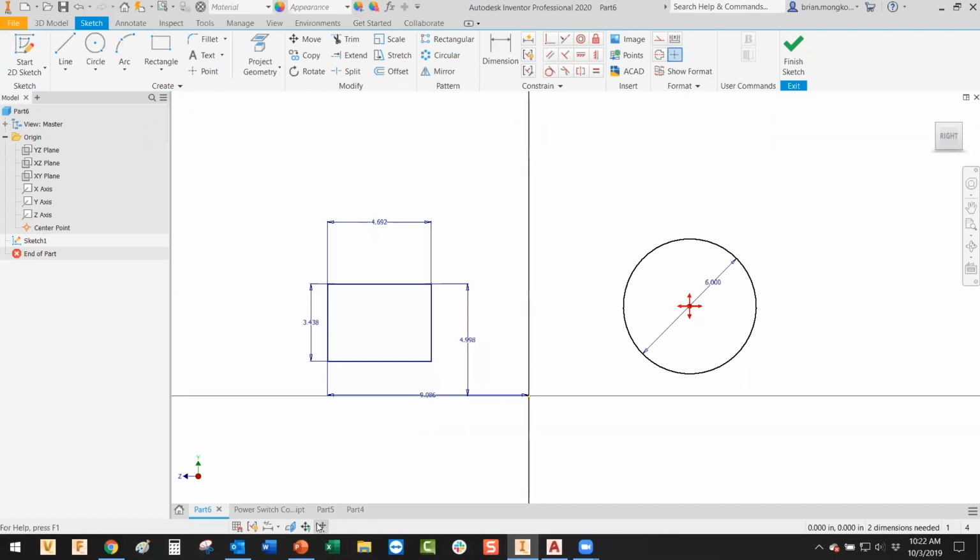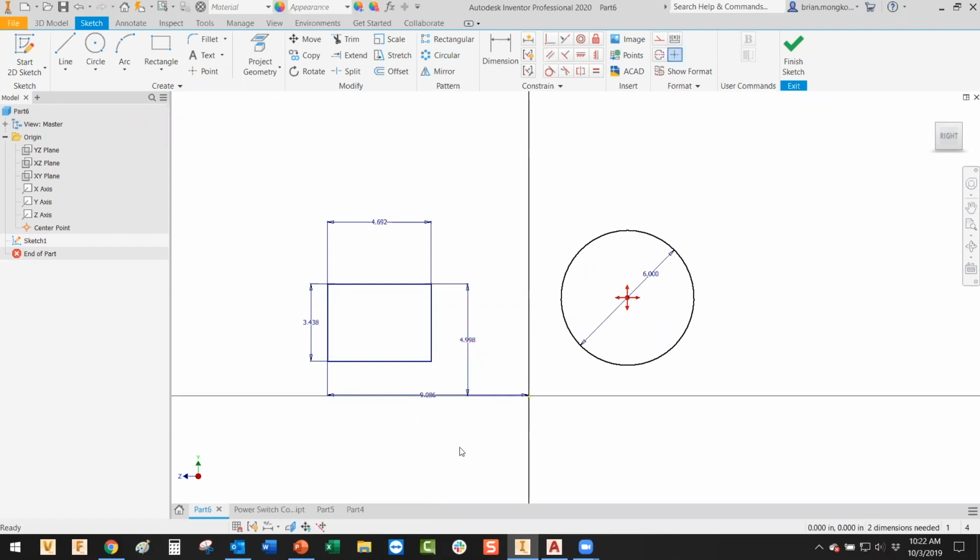Yeah, I think this is underused sometimes, and people forget about that. But when you're sketching and defining your sketch and you're almost done, just turn this on and see where else it's missing. I just lock it. I'm bad. I always just select fix in place and lock everything. Yeah, but you probably want to dimension it for best practices there.